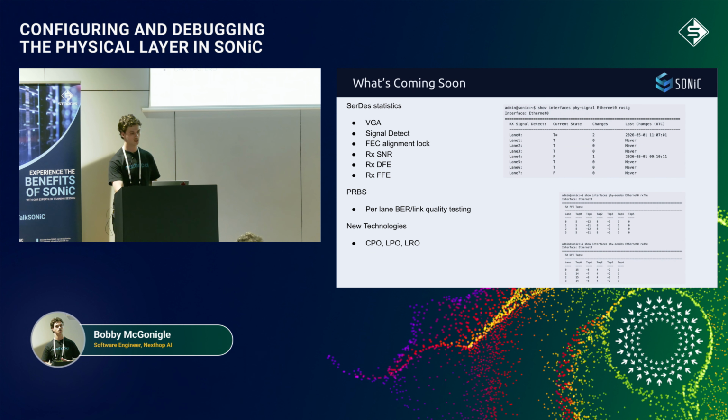So looking forward, there's a deeper push for SerDes-side visibility. There's been a bit of a shift. It's great that we have these transceiver debug outputs and we can take a look at the module, but a lot of that information comes from the digital signal processor on these optics. A lot of the emerging technologies right now are getting away with the DSP in these modules and putting all of the work of cleaning up the signal on both the TX and the RX path on the SerDes now that they're more capable. So having that SerDes statistics and being able to look at what's going on in the SerDes is incredibly important for what's going on and what's coming in the future.